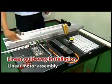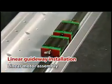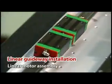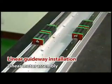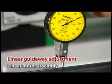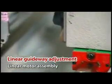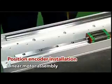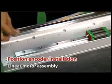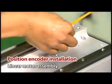Guideway installation. The guideway serves to direct linear motion. As the forcer travels, the guideway maintains the gap between the forcer and stator. Guideway adjustment adjusts the linearity and parallelism of the guideway, improving the platform's positioning characteristics. Position encoder installation. The position encoder is the chief method of ensuring positioning accuracy and is the basis for motor servo control.